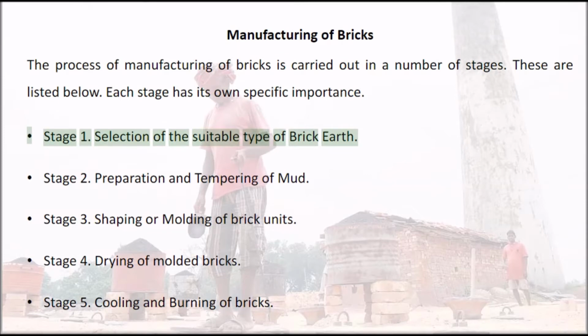Stage 1. Selection of the suitable type of brick earth. Stage 2. Preparation and tempering of mud. Stage 3. Shaping or molding of brick units. Stage 4. Drying of molded bricks. Stage 5. Cooling and burning of bricks.